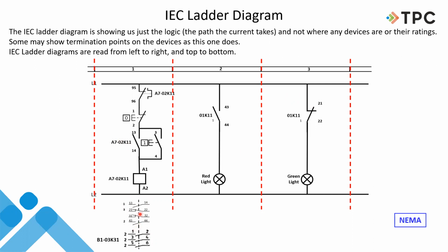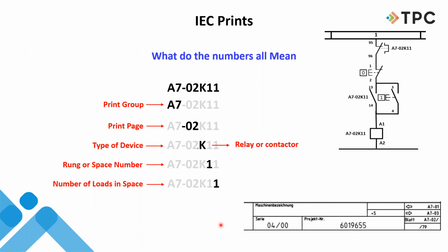But down here, connected to that, I've got some power contacts, and power contacts are always single-digit numbers. So on a different drawing, on B1, because you see this is A7, in a different group, B1 is where this set of contacts are being used. So I got to go to group B and find this, but it's telling me that this is a contactor with auxiliaries. This is telling me that I got a red light and I got a green light. Lots of information and rungs. So we're trying to connect everything together. So here's how we're connecting it together.